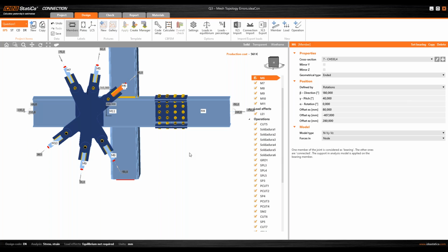Check the units, and then there is another common issue, and it is because sometimes in our DXF file we have modeled the geometry with a polyline, or maybe it's a block. So it is a very recommended practice to explode the polyline or the block before importing, and get individual lines. It's better. And then there is another funny topic related to this.